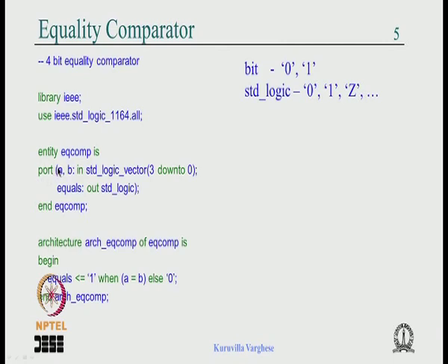You open the port with parentheses, left and right, and a semicolon. All the syntax is terminated by a semicolon. If you describe a complete entity, you put a semicolon, a complete port, you put a semicolon. Every statement, every body is terminated by a semicolon.